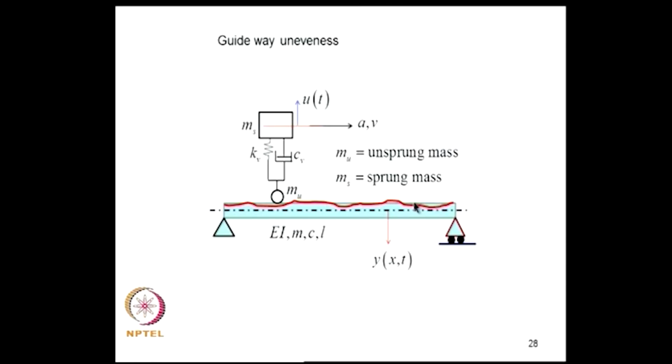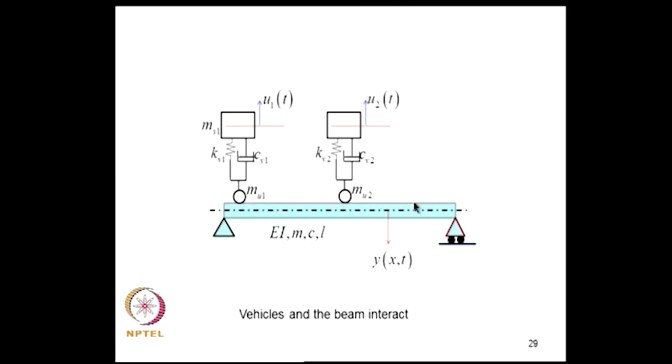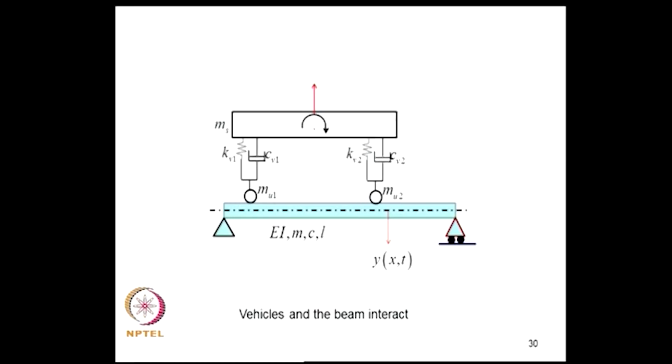So, this can also be included in our model, and there could be a series of loads crossing the bridge. So again the principle of superposition will not be valid here. By that I mean if you find the bridge-vehicle system response due to passage of one vehicle and a similar response for passage of another vehicle, that cannot be superposed to find the response when both the vehicles pass the bridge. That principle of superposition is not acceptable.